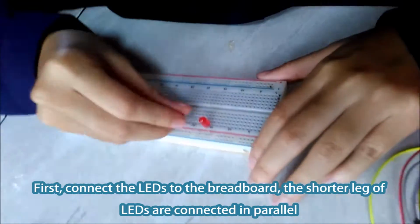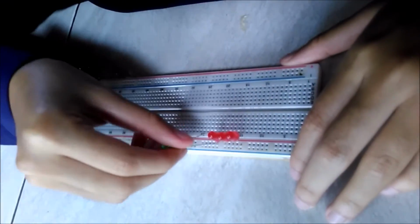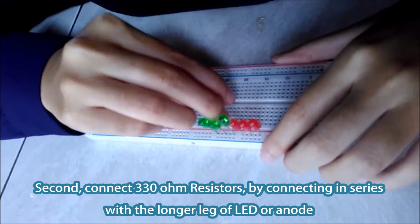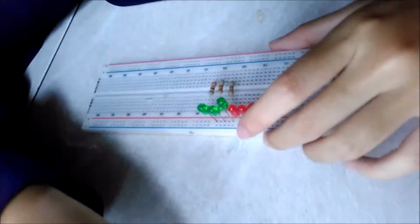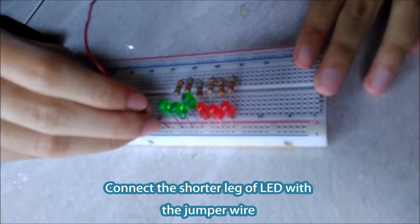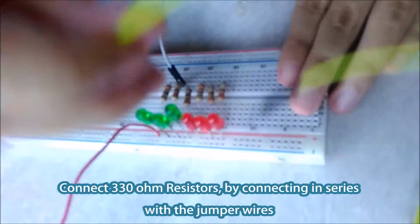First, connect the LEDs to the breadboard. The shorter legs of the LEDs are connected in parallel. Second, connect a 330 ohm resistor in series with the longer leg of the LED, or anode. Connect the shorter leg of the LED with the jumper wire. Connect a 330 ohm resistor in series with the jumper wires.